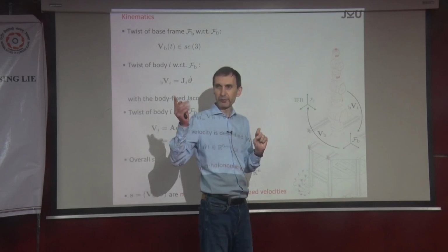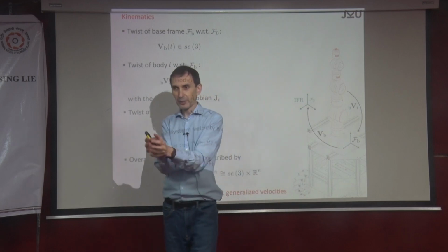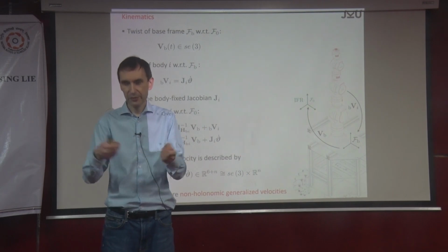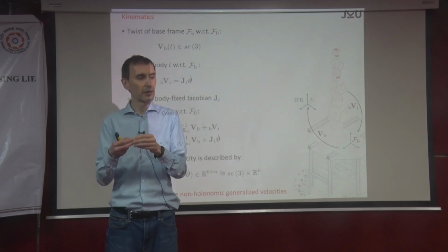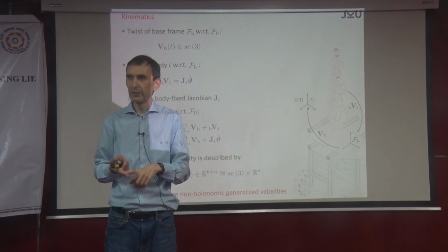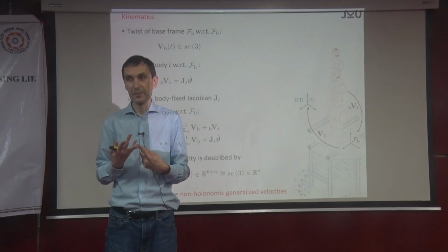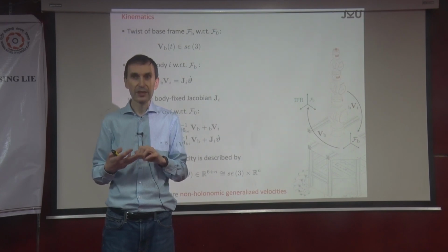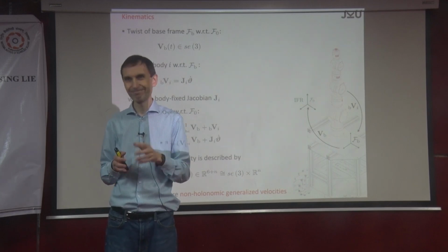So good point, what can you measure actually? You have a control system. You have your robot, and you can do motion planning, right? You say go from there to there, and somehow it does it. So from your control system, what quantities can you access? The angle of rotation, the speed of your joints. What else? Torque. Can we measure torque? Yeah, and that's the thing. It's not always easy to get it, but you get the torque.